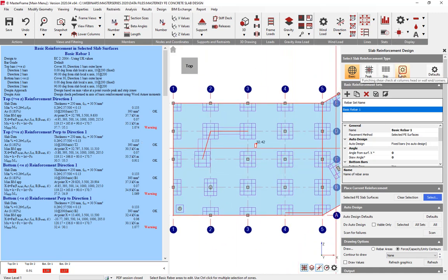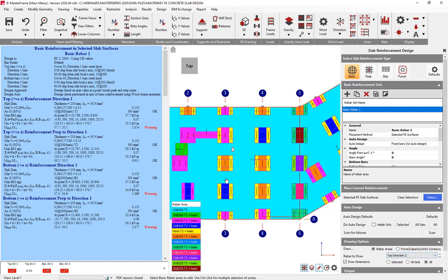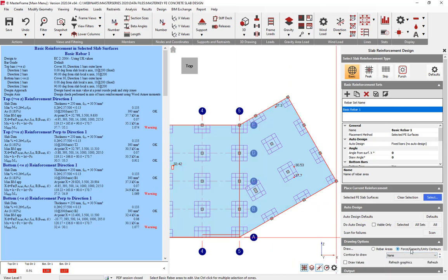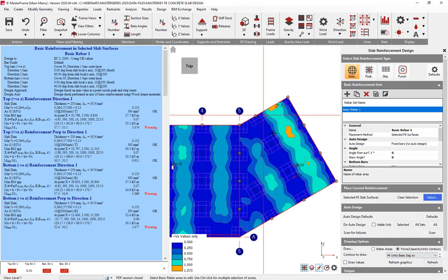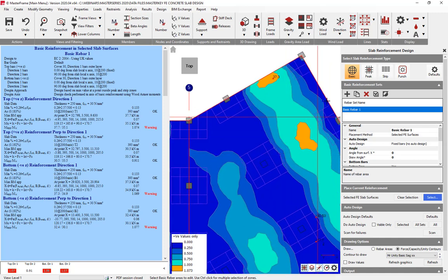Great. So having established obviously my main reinforcement, we did have a little problem still in the basic area here. So just to remind ourselves, when we look at the sagging in the X and refresh that, we've got some areas here where the basic rebar isn't adequate. Now there's obviously various things you could do. We could place a strip of rebar in here, providing additional rebar in these areas. Just like we placed the strip over the top of the wall, we can place a strip where the bars run parallel to the strip line and are on the bottom. That would be one solution.